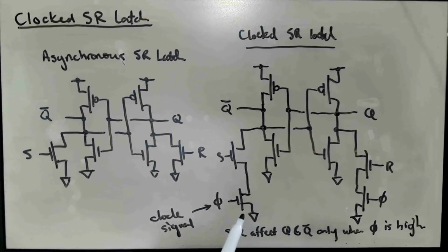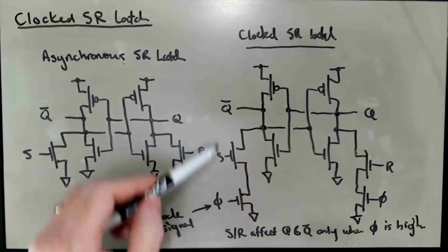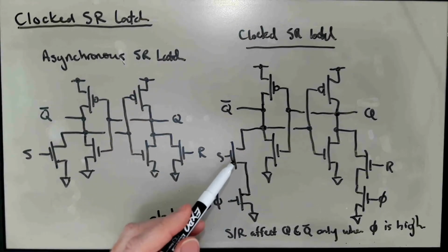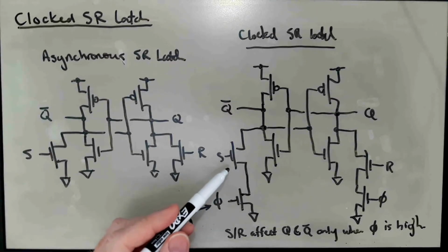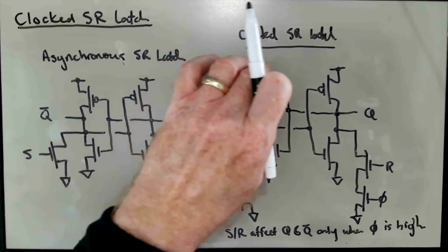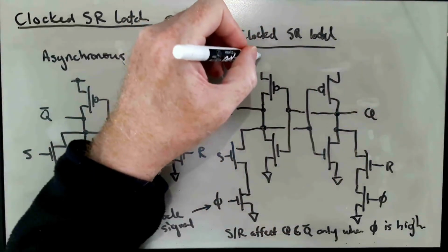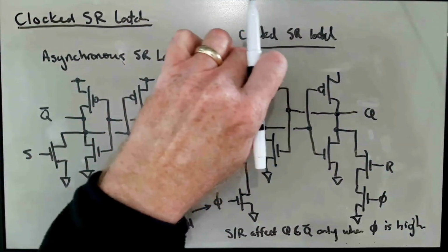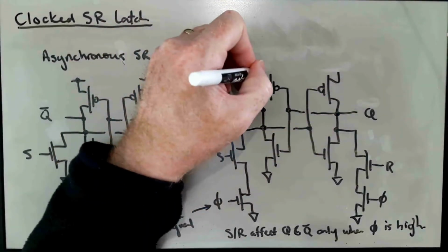If we wanted to think about each half of this SR latch as a complementary CMOS gate, and go through the same exercise whereby we remove the writability problem, we could do that same thing. What we would find we would have to add to eliminate the writability problem is a parallel connection of two transistors up here. I will need to give myself a little bit more space, obviously.